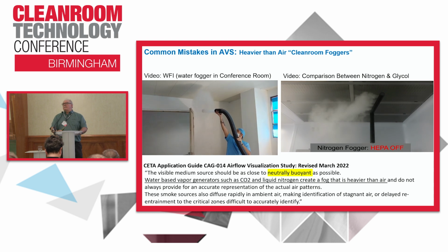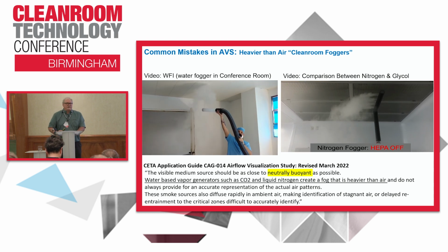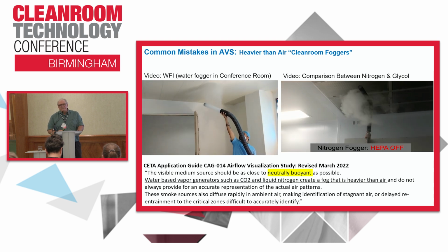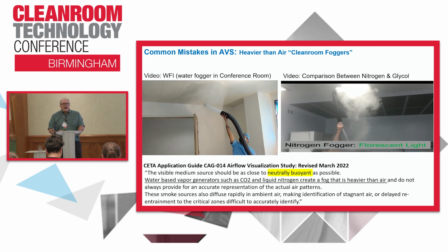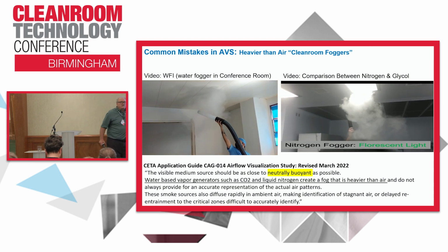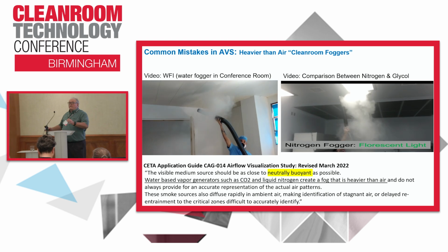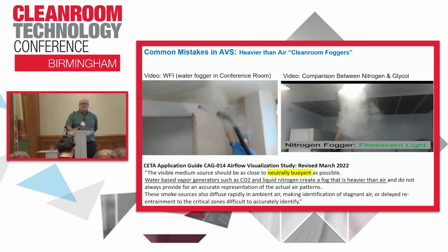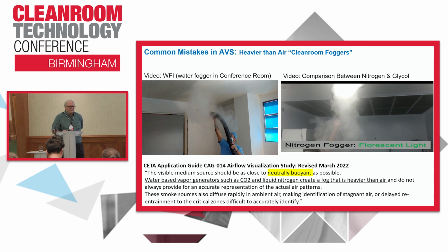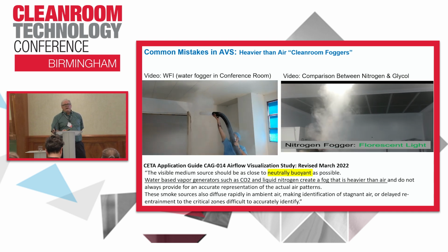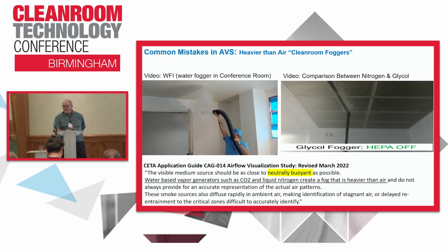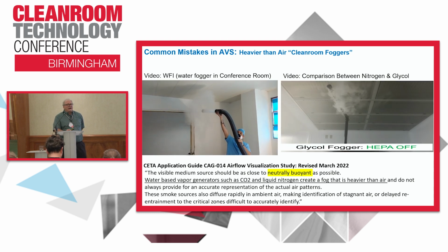Right? People like to talk about cleanliness when it comes to smoke studies. It's clean. I want to be clear to everybody. There's nothing clean about doing a smoke study. And why is that? Forget if we're using water, nitrogen, or a smokeless system. What are we doing when we're doing a smoke study? We're simulating our operations. If you have a filling line, you're going to simulate all your interventions, corrective interventions, spills, broken glass, setup and assembly.